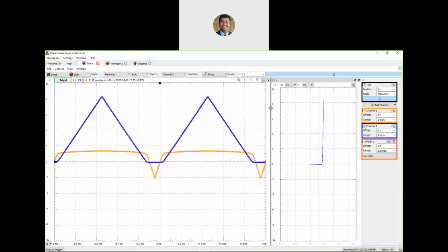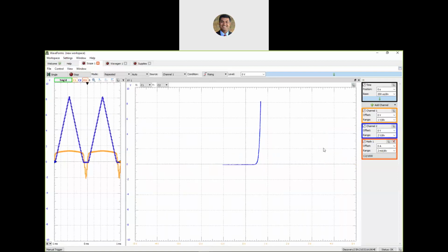and maybe zoom over here, increase the width to maybe 3, maybe even 4 here. And on the x-axis, I have it default as channel 1. Yes, I want that to be channel 1 because the x-axis is voltage across the diode, and that's what I want it to be. The y-axis is not channel 2. I actually want that to be the current through the diode, so M1.